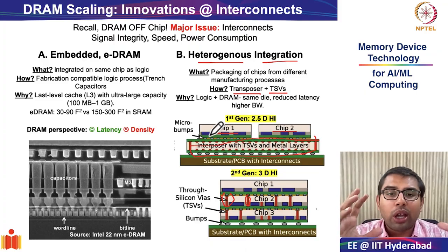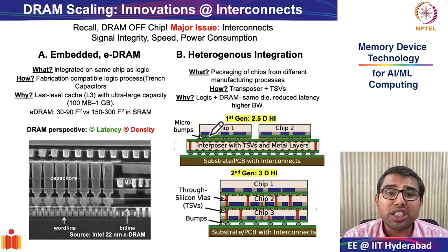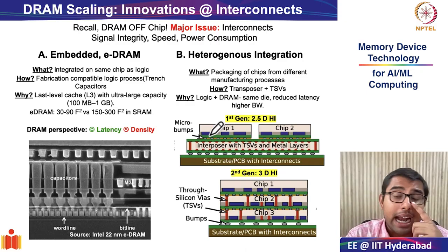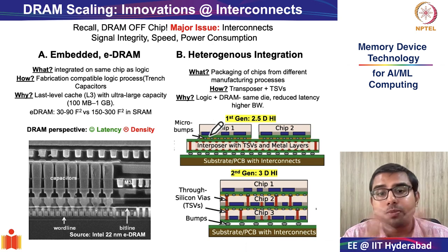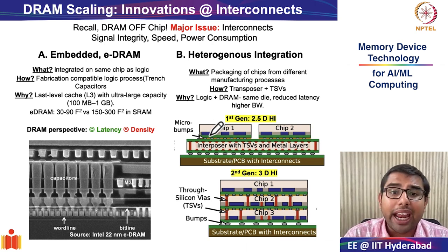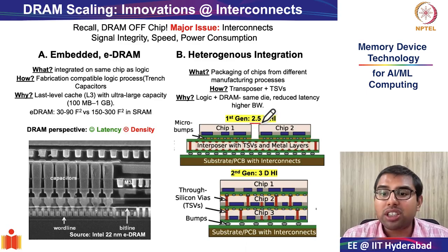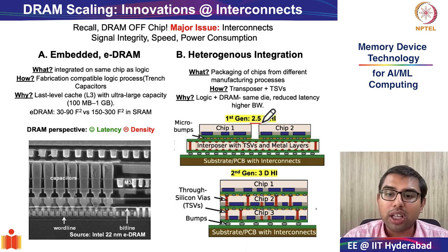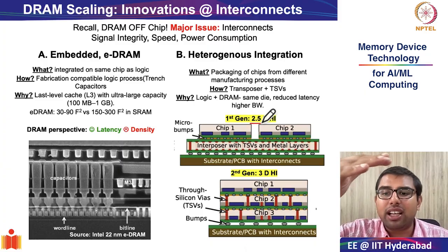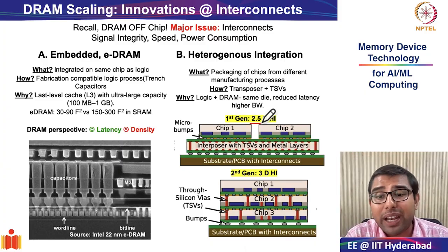Okay, so the first generation of heterogeneous integration was very successful, and AMD already has a product called high bandwidth memory. I suggest you go and read more about it. This heterogeneous integration in 2.5D places multiple chips side by side on a common interposer, thus enabling very high bandwidth connections without vertical stacking. This simplifies a lot of the fabrication processing and also thermal management.